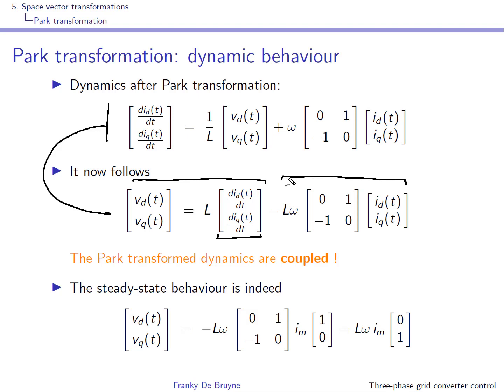So this Park transform introduces this additional term, and you can see that it introduces a coupling effect. The voltage, or the D component of the voltage, depends on the D component of the current, but it also depends on the Q component of the current. So indeed the two differential equations are coupled.